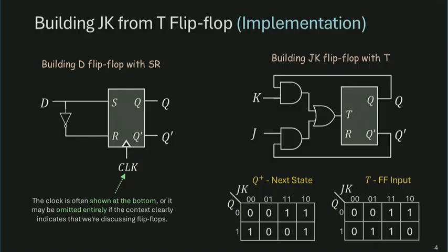What about a more complicated example? Let's say if I want to build a JK flip-flop from a T flip-flop. So T flip-flop is a sequential component. It's actually also like a tiny little sequential machine. Same goes for JK. So JK is like a small sequential circuit whose behavior is defined by the characteristic equation of the JK flip-flop. So now we're really trying to build a small sequential circuit using a T flip-flop. And this is what we do. Right, we need to add on some additional combinational logic at the flip-flop inputs to make that conversion happen. So this is called the next state logic. It's also called the glue logic, a way to glue together a component with the input-output interface to realize the functionality of a different component.